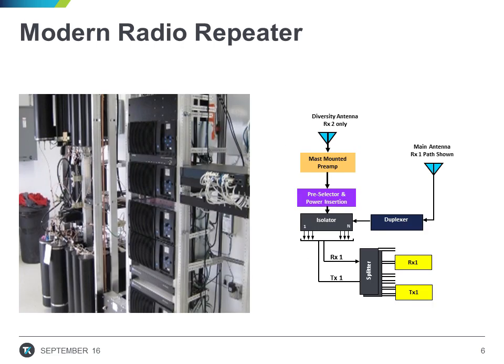Modern radio repeaters are quite a bit different than the simplified block diagram shown in the previous slide. Here we can see where we have diversified receive and transmit antennas, as well as a receive multicoupler. In this instance, it's much more complex for us to describe the full operation of the radio repeater. There are many interconnects and different paths for the radio frequency to follow.